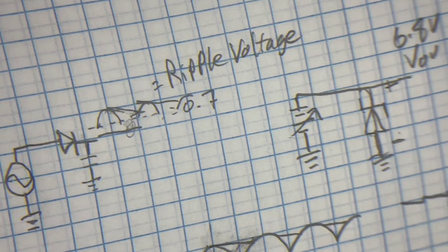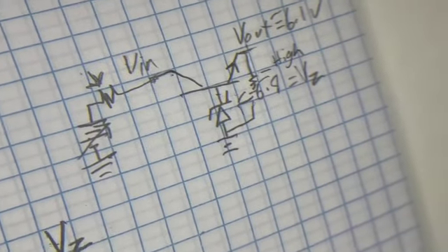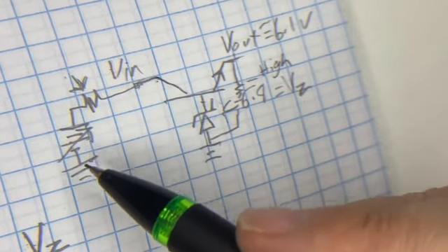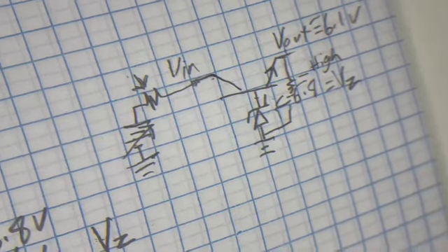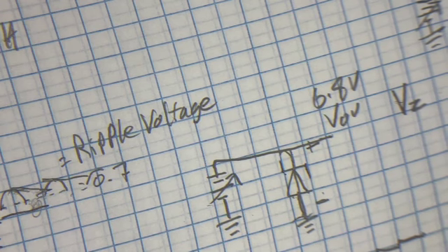But it's a real solid circuit. Oh, I should probably put that so you can see what I drew. High impedance here, moderate impedance here, some voltage source here. And this is also going to determine your dropout voltage, which is an important thing to know about voltage regulators, because you have to have a certain voltage above what you're trying to get out in order to get a regulated voltage.